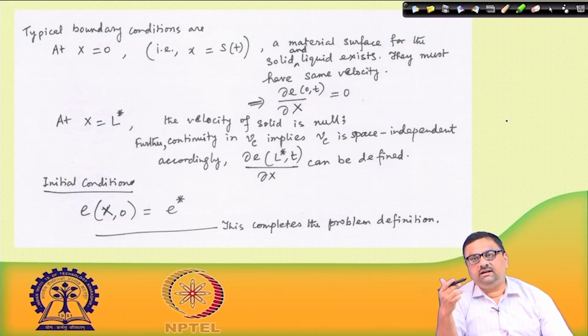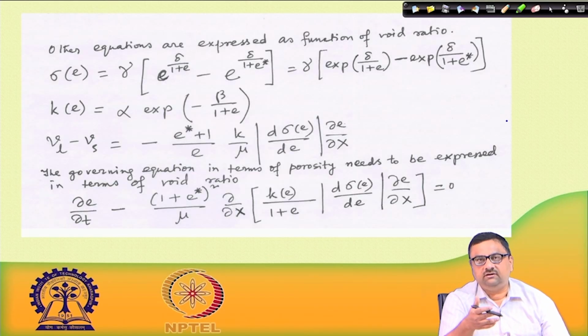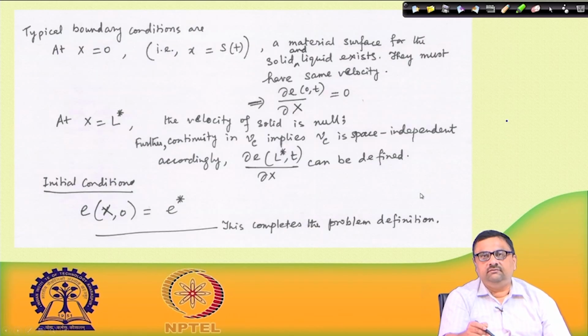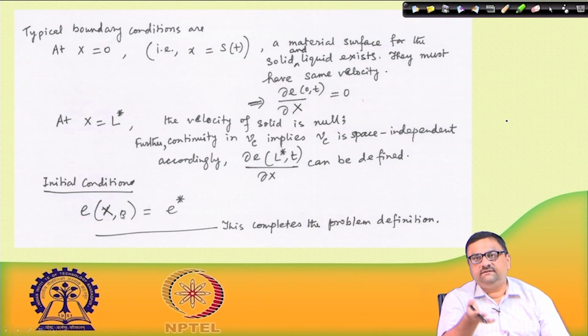So, what all did we rely on so far? We relied on constitutive equations, on equations for permeability and excess stress, and those equations have some system parameters that need to be determined experimentally or from a priori information from other research work that has already been done. Then one has to solve the governing equation I mentioned just now, with these boundary conditions and this initial condition. So, this gives me a solution of E.